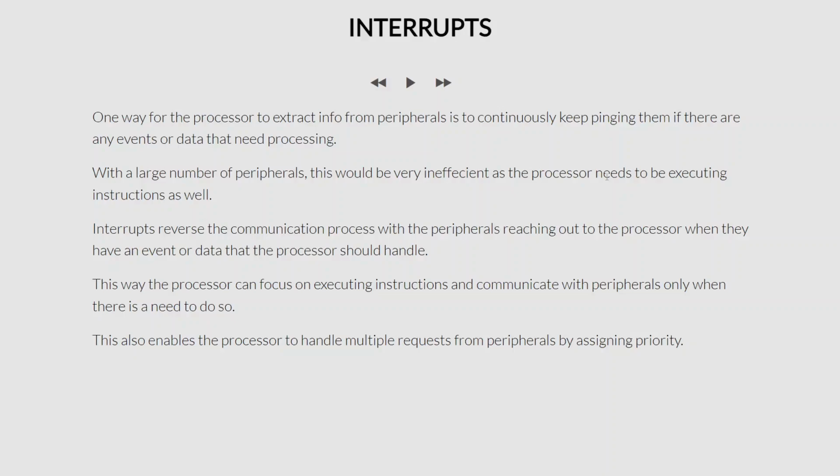We saw in the previous lecture that there is a TIE bit on the timer control register, which if it is set, then an interrupt will be issued when the timer counter decrements to 0. Now, in this lecture, I'm going to talk about the significance of interrupts and how interrupts are handled by the F28069 processor.